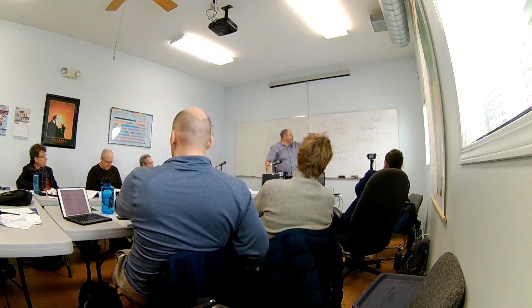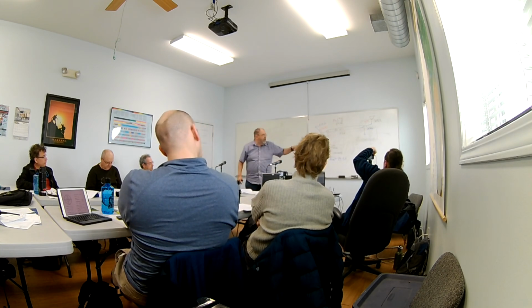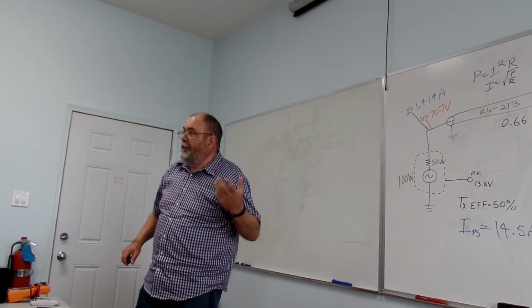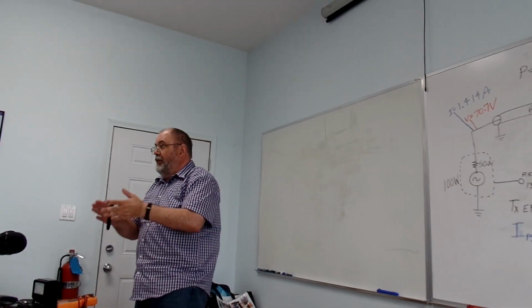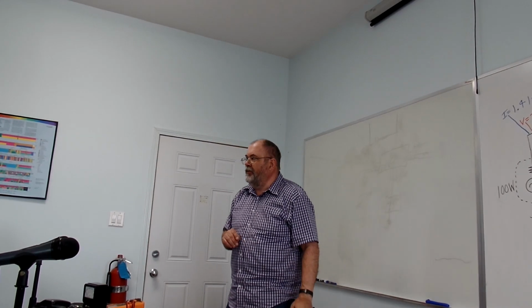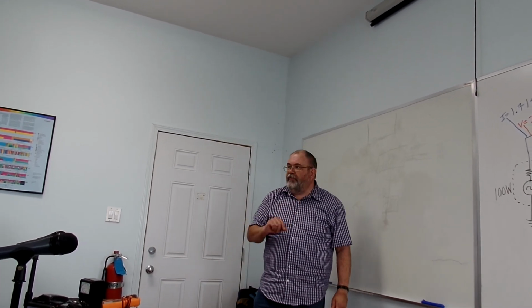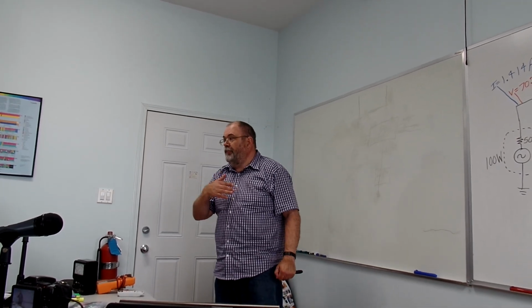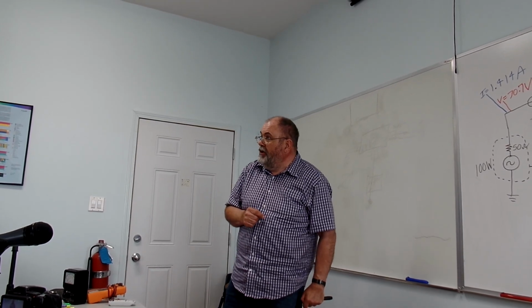But as soon as we change out the medium that the RF is traveling through, in the case of RG213, it's a polyethylene plastic. It's like garbage bags, that kind of plastic. The RF travels slower through it because now there's some solid matter to go through. There's some molecules in the way and it actually slows down. So it is 0.66, 66%. That's still bloody fast, but it's a lot slower than the speed of light.